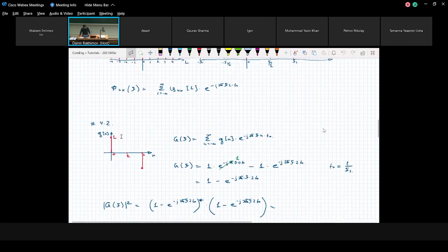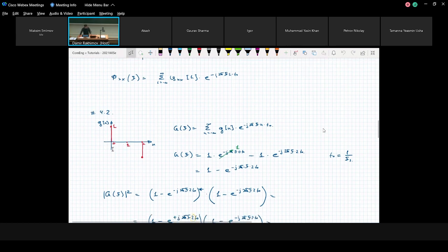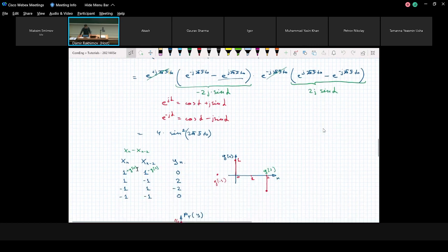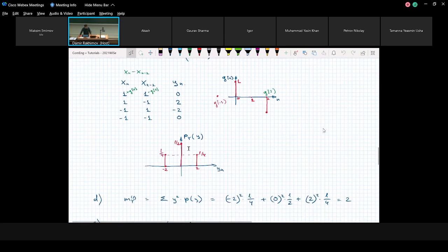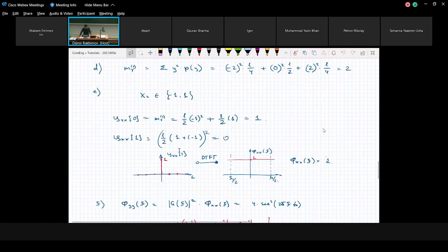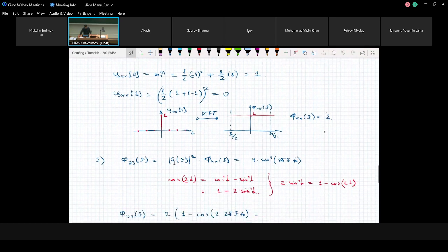Then we considered the case where we perform filtering on our sequence, and we check how filtering influences our transmission. We assume that we have transmission of only two symbols, 1 and -1. After filtering, this is our alphabet. We have three possible cases: -2, 0, and 2, with different probabilities. Calculate how the autocorrelation function will look. The original function is just a delta pulse.